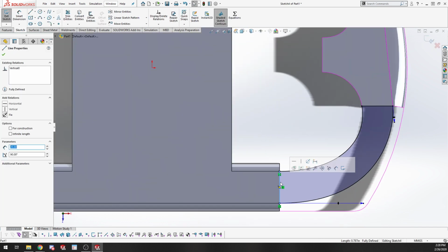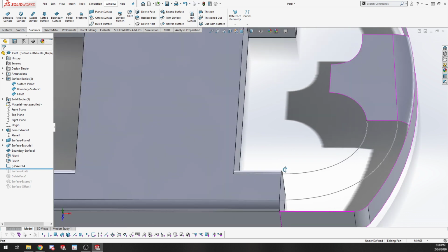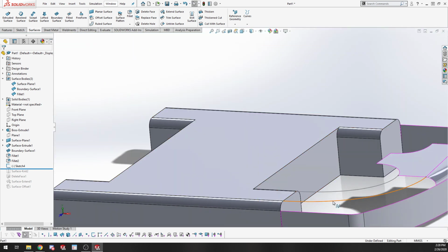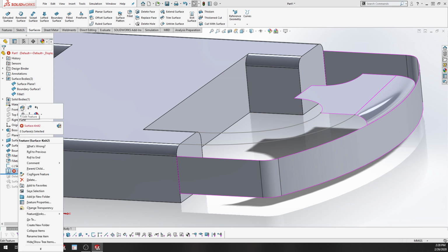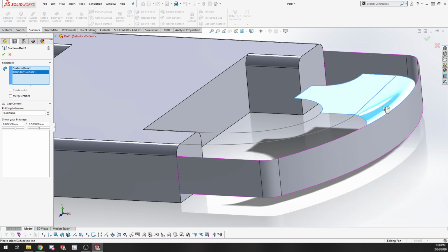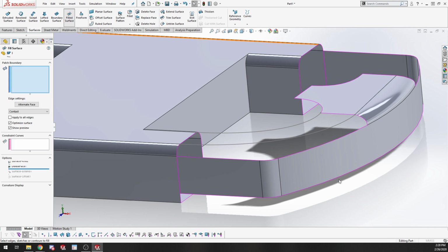So I can actually go through and make, if I go into the sketch again, delete these lines. Remember with that planar surface, I had to actually have an enclosed boundary that I worked with. Here I don't. Sometimes in surfaces I'll just have these random curves floating around in midair. And if I wanted to create that filled surface that we did before, let's see if it'll rebuild nicely. Probably won't. I'll have to go through and create some of this stuff again. We'll knit that together. Talk about the delete face. Yeah, so now I can add in a filled surface here.